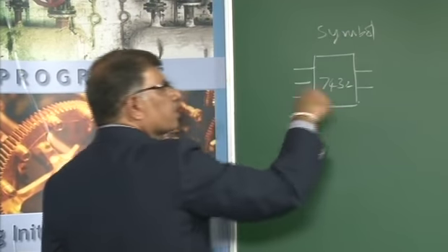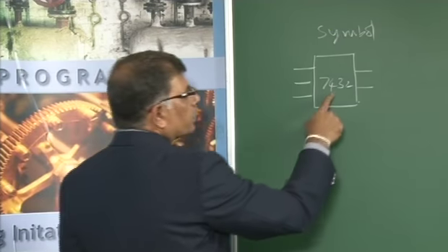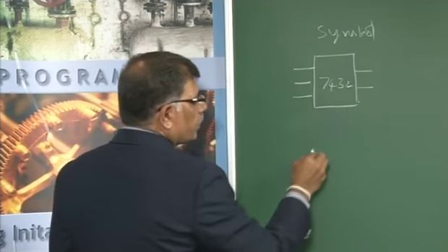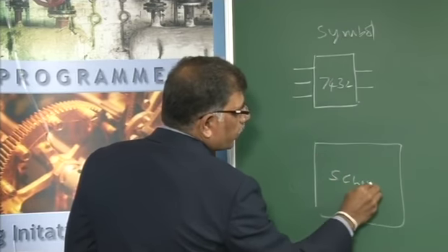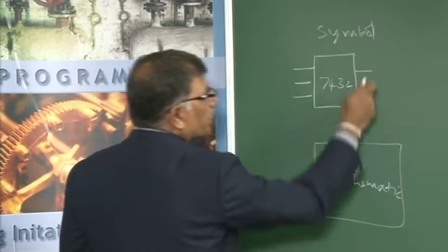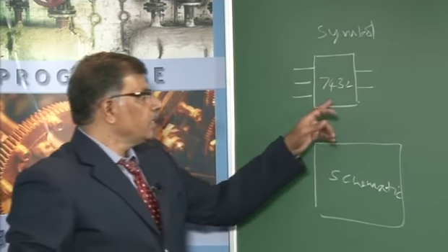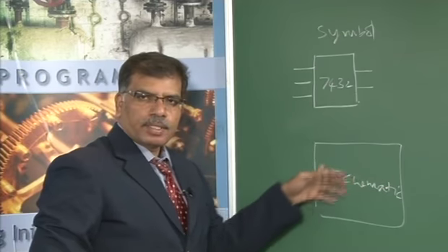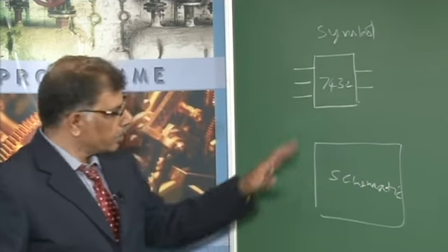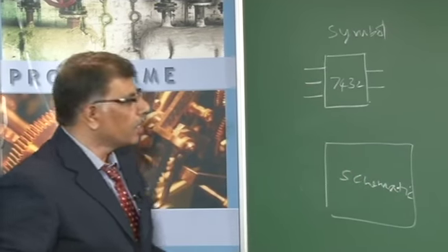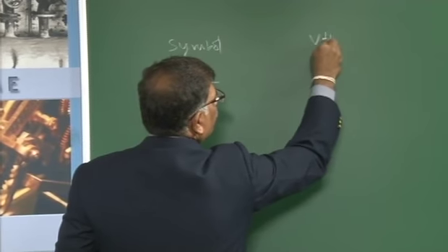Inside the symbol we have circuitry which tells how the symbol works, which we call a schematic. The schema of interconnecting the logic gates to get the required output is nothing but a schematic. So internally this IC has a digital circuit interconnection which specifies the behavior of the symbol. This is just the traditional representation of any hardware circuit. So this I will try to convert into the VHDL language.